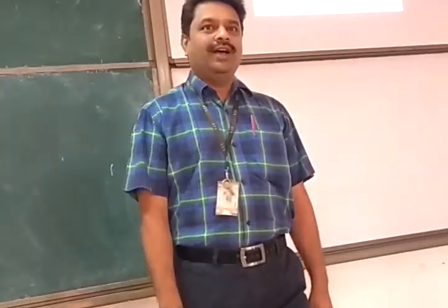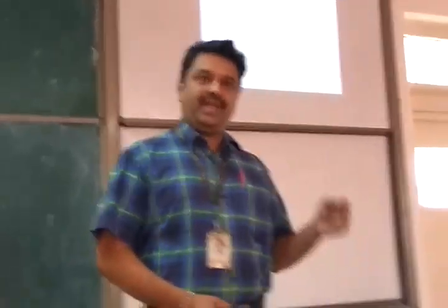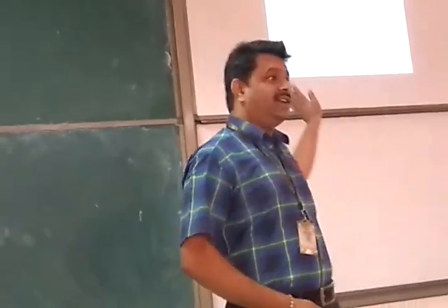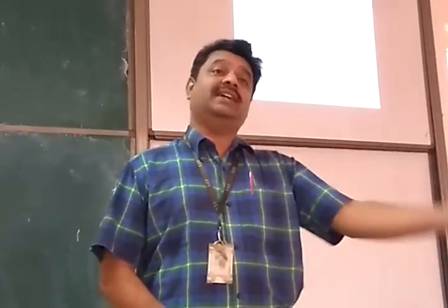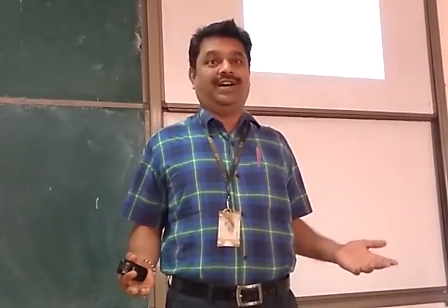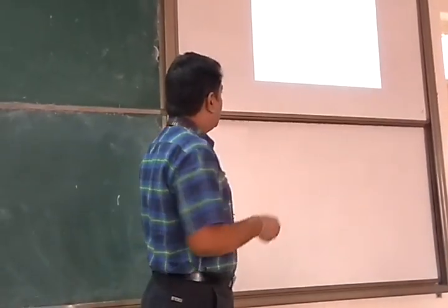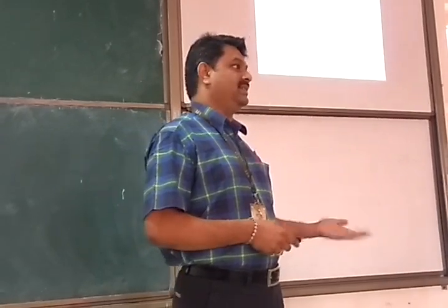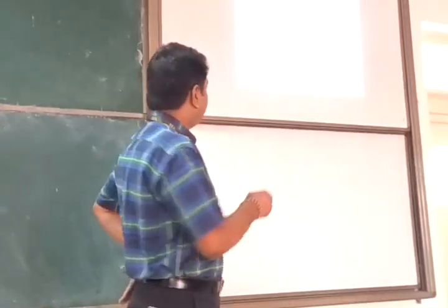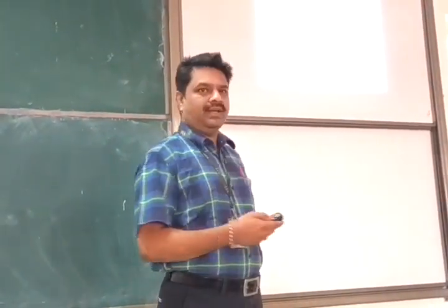In fact, 100 measurements we have made, and 50.651 is not there in the table at all. But then we assign that as the diameter for that particular shaft. You imagine our poor state. Okay. So 50.651 will be assigned as the diameter of the shaft because that is the arithmetic mean.